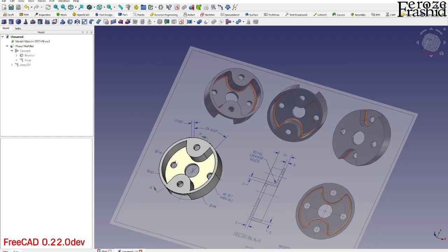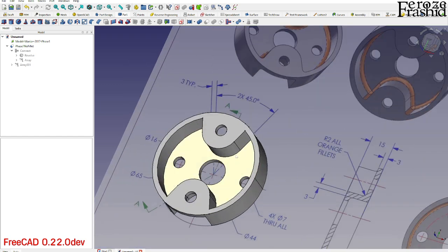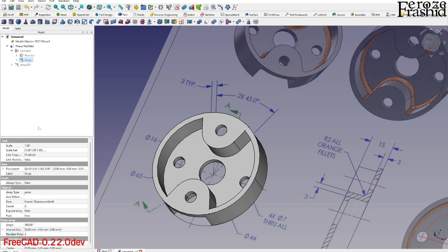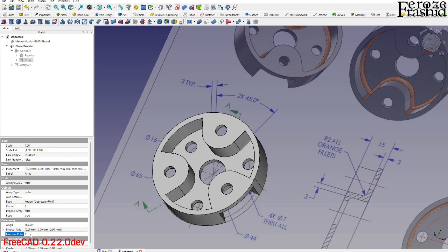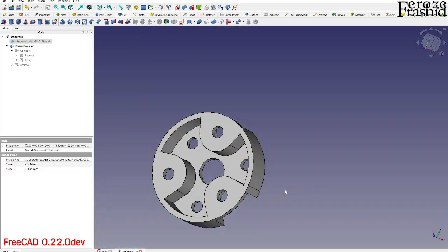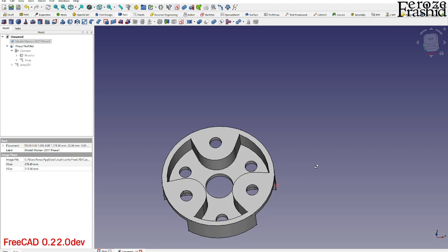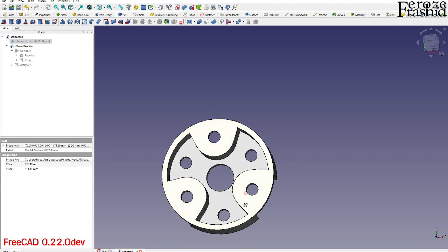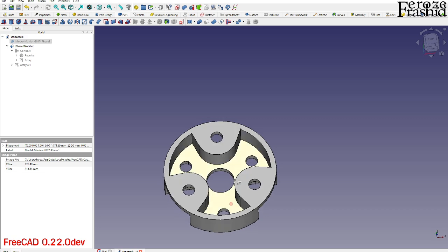And before I apply the fillet, I want to do a trial. I want to go into array and change this. So I cannot change this count. It comes from number of polar units. So I'm going to come here and say make it 3. Look at that. So what it does is, now it's repeating 3 times with 3 times total 6 cylindrical holes in there.